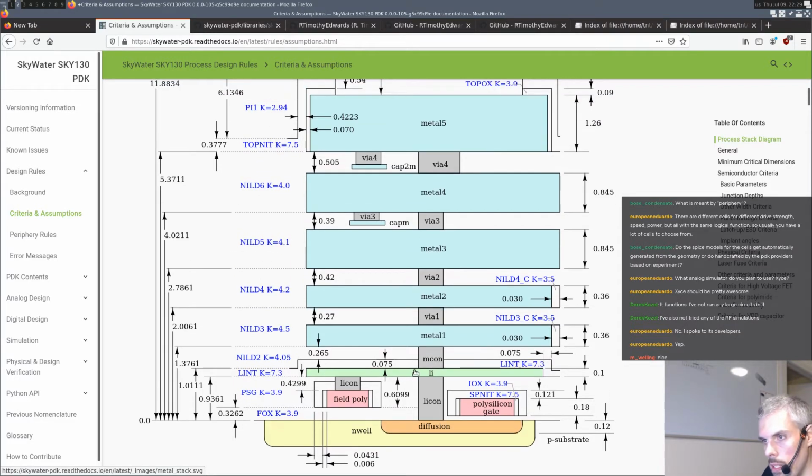And then you have the various layers of interconnect, and they have this thing called local interconnect, which is slightly different from the other metal. Apparently, what Tim Edwards told me is that it's basically a high resistivity metal layer. I'm not entirely sure which metal metal 1 to metal 5 is, whether copper or aluminum.